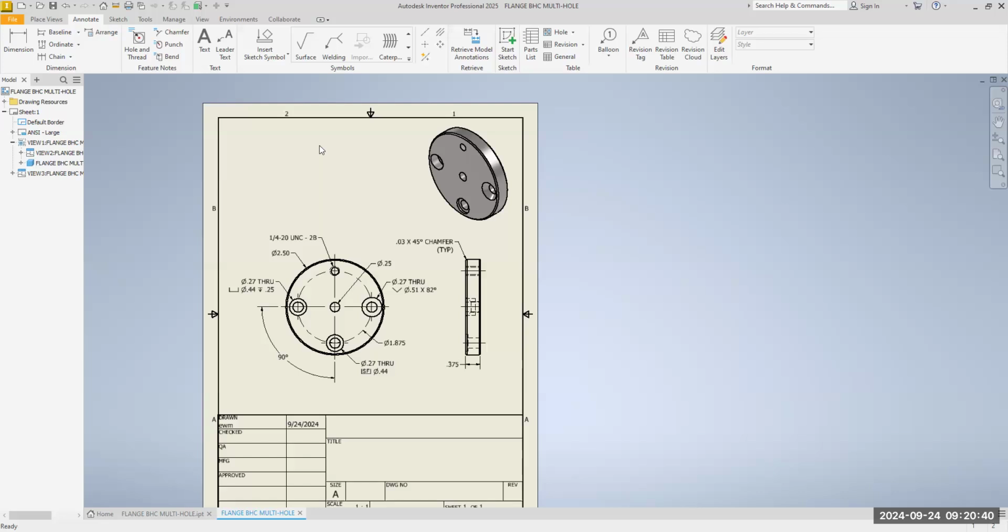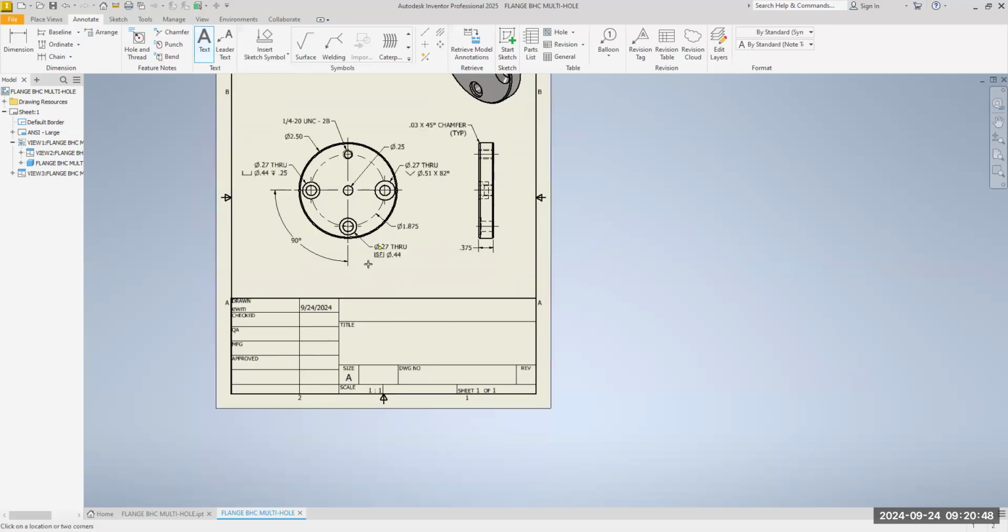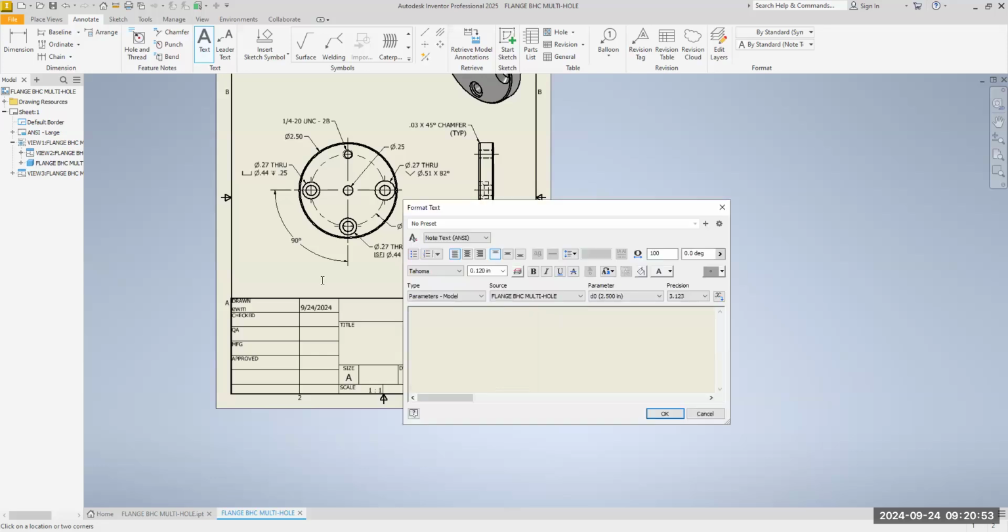All right. Something I require you to do, but industry does not require you to do this. Go to text and go below each view. We're going to go below the front view. Click, and just like Word now, it's like Word. You're going to type in front view. You're going to hold down the left mouse button, highlight it, make it bold, underline. Okay. Just like you're working with Word.